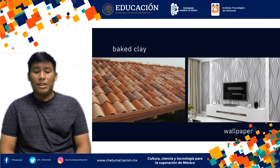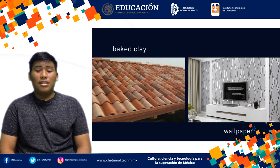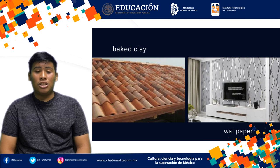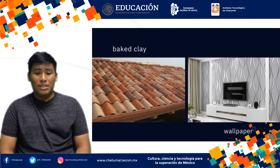Cooked clay is a material that adds a rustic and traditional style to the spaces. It is mainly used in floors and facades. The characteristics of this material are that it is porous and has a warm appearance, very popular in rural areas or constructions with an ecological approach. Cooked clay is ideal for warm climates because it maintains freshness in the interiors. Its installation and maintenance: it is installed similarly to ceramics, but requires sealants to protect it from moisture and stains.